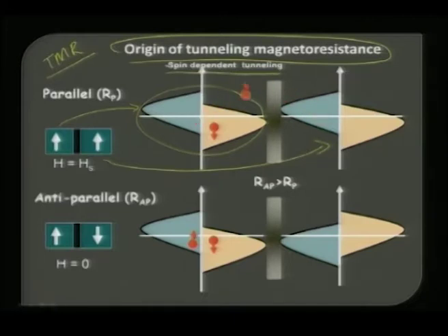The upspin electrons can easily hop to this one, and the same is true for the downspin electrons. They will happily go across the insulating layer. In this case, this is a small barrier. It will tunnel through this small barrier to the other ferromagnetic layer.